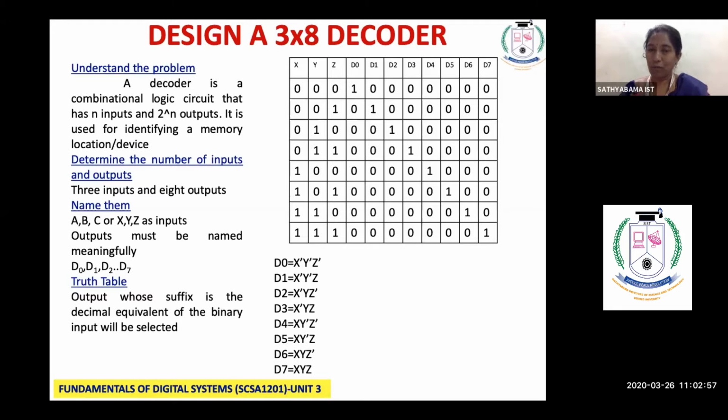So instead of one wire, I have to use 2 wires. If I use 2 wires, then I will have 4 combinations. It will be 0 0, 0 1, 1 0, or 1 1, 4 combinations. So indirectly, I am leading you to the definition of a decoder. I am repeating it again, you check. If you have 2 devices, you need 1 wire. If you have 4 devices, we need 2 wires.